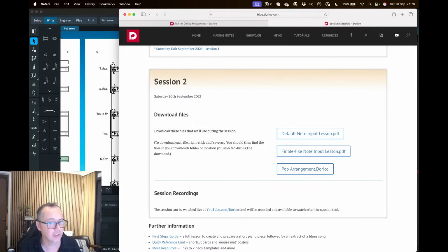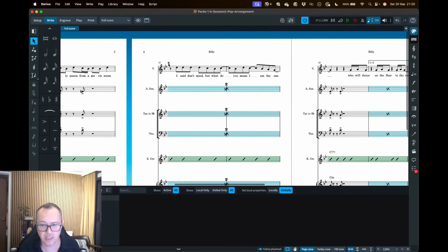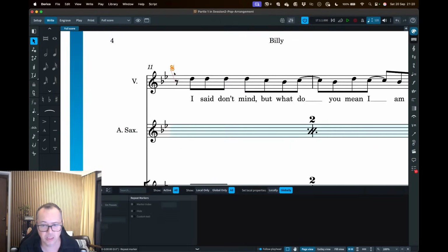Somebody's asked about changing the size of a couple of things. Every time I've looked for these symbols and what size they should be, they're not normally published as large as people seem to think they are, but you can change them. If you choose this one here, there are a couple of options for changing it, and in particular you can have a custom scale down here. If you made this 200%, it's going to be a lot bigger.